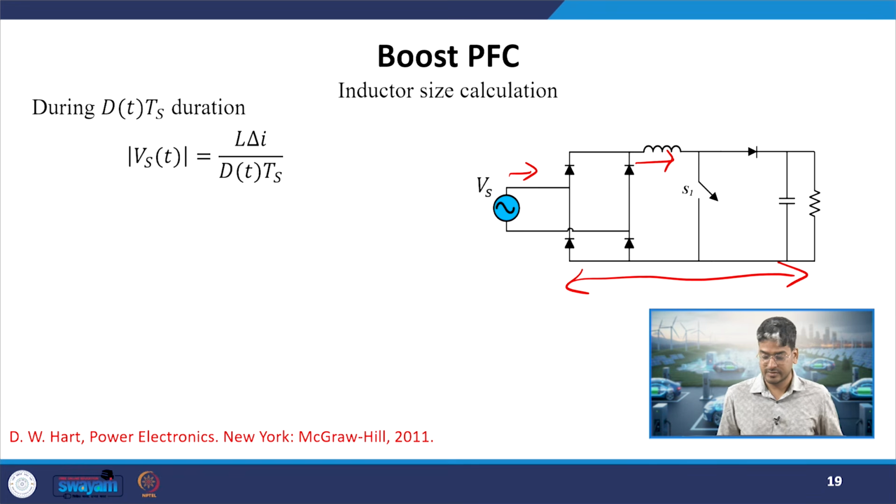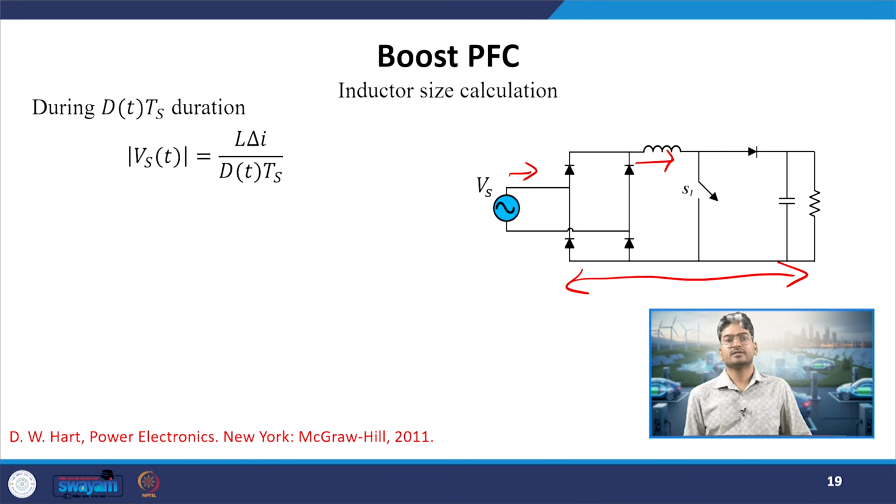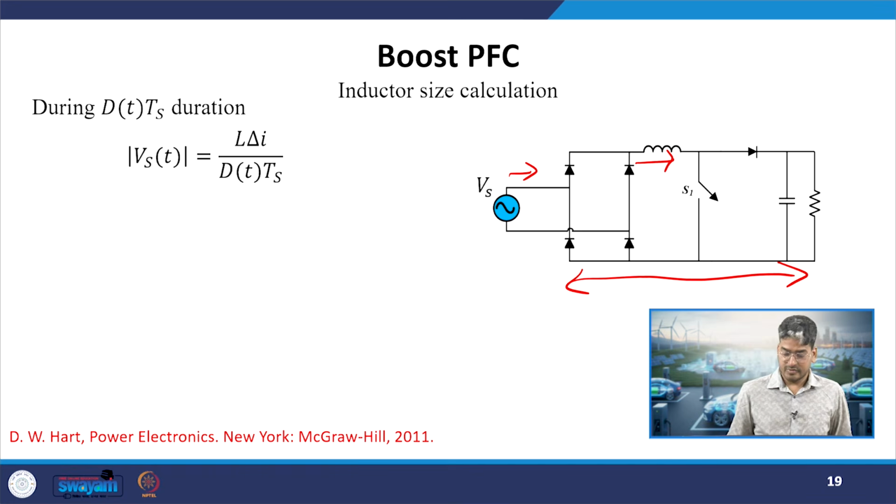It is the simplest power factor correction circuit. We have seen the duty ratio variation and how it is related to your input voltage. We will continue with our discussion and design the inductor in our next session.